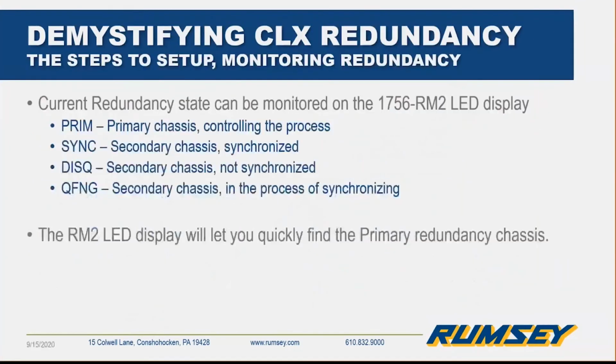Monitoring. These are four different displays that the RM2 LED will show. The primary and sync I talked about, but disqualified and qualifying are okay too. Those are not usually a problem unless it's hanging there for minutes upon minutes. So if you set this all up and you see either disqualified or qualifying, those bottom two abbreviations, then you have to look into something. But it's normal if you just do a switch and then, while the secondary is being requalified, you'll see those kinds of indications.